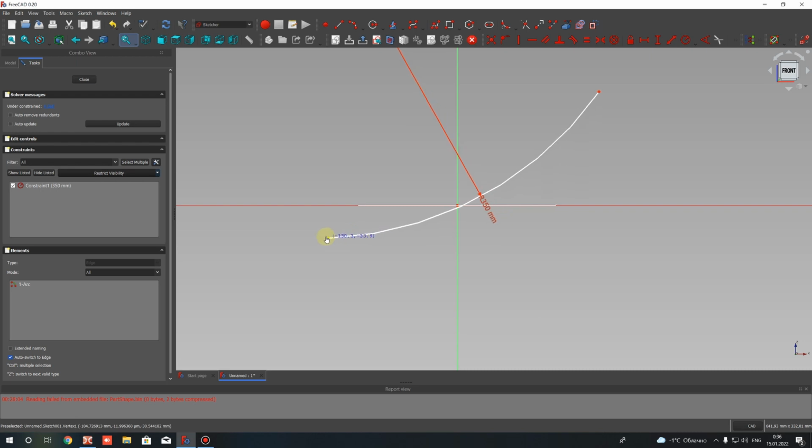You can make it manually, the angles of this are not so important, because it's a propeller, and we can change angles of the 3D model. We can do a twist of our blade and change the position of the blade in future. Okay, let's choose something like this. I'll make it somewhat smaller here and close it.